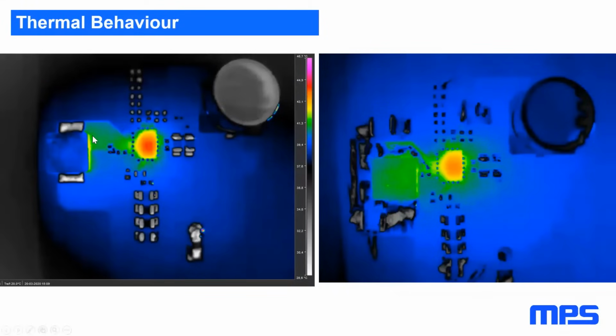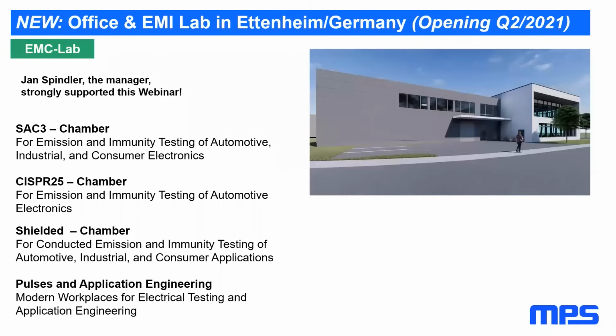For thermal, of course, it's better to have a larger switch node for heat sinking of the coil and transfer from the chip. With a reduced size switch node, the self-heating is quicker.